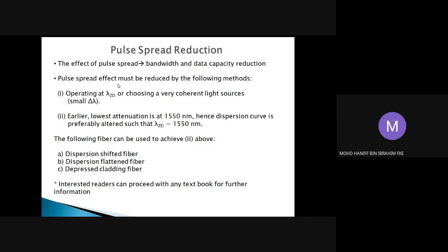So we can further work at this lowest attenuation region of 1550 nanometer by simply shifting the dispersion curve so the zero dispersion wavelength is at 1550 nanometer.